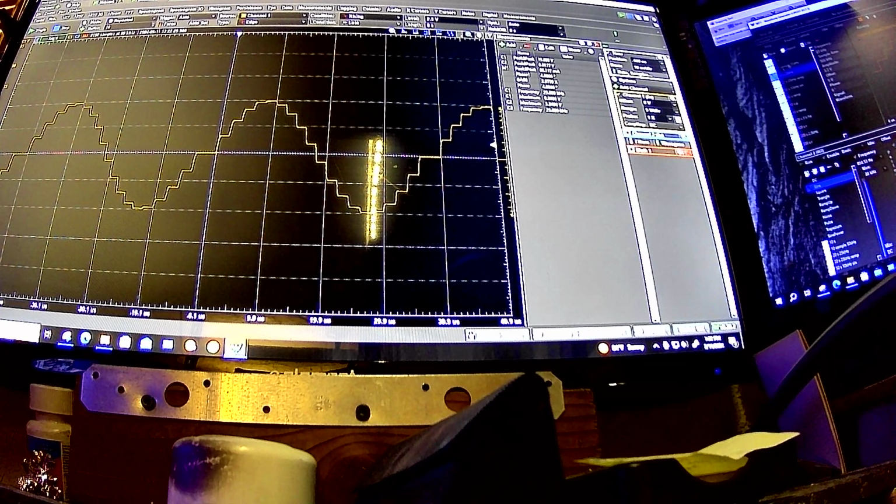If I wanted to make it, instead of 25 kilohertz, like 24 kilohertz, you're going to really have to change your waveform equations every time you change the frequency, because it's going to change the wave shape a bit, because you still only have so many samples to work with. Right now we're working with 20 samples, so that doesn't give you a lot of variability if you're trying to make subtle changes in your frequency, but that's a different issue. The more samples you have to work with, the easier it is to make adjustments like that.